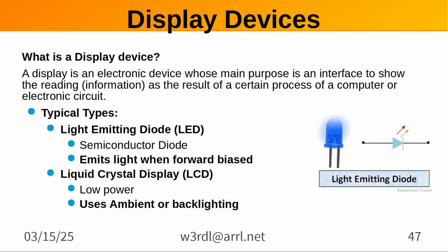Normally they have an LCD display. It may be color, may be monochrome. And it can use either ambient light or backlight, depending on the LCD array. If it uses ambient light as a reflective one, they tend to work better out in the sunshine because you get contrast. The backlight doesn't work too good in the sun.